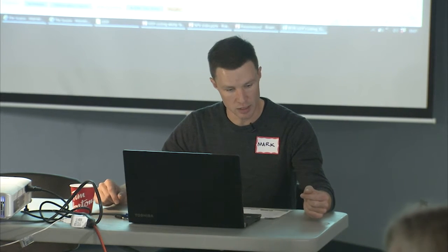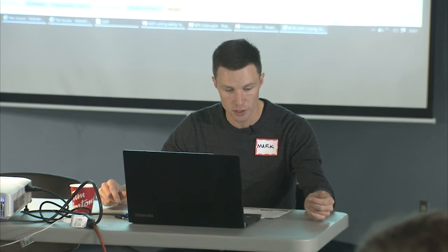Okay, so with this table up, we're going to change the drywall price to 20 cents a square foot for the material and 40 cents a square foot for the labor. So if you look up on the screen for a moment, you can see where I'm putting in these costs. You don't actually type over the unit cost, you type in the cost adjustment, which is the field beside it that's blank. So we're going to type 20 cents or 0.2 into the cost adjustment for the material.